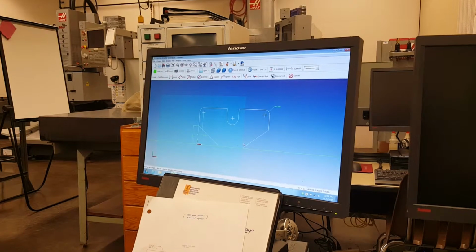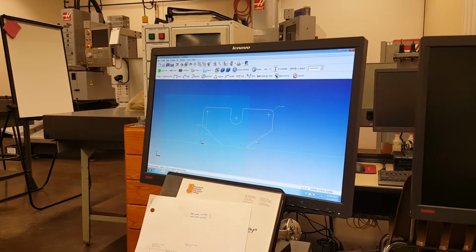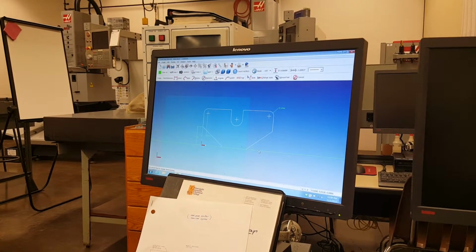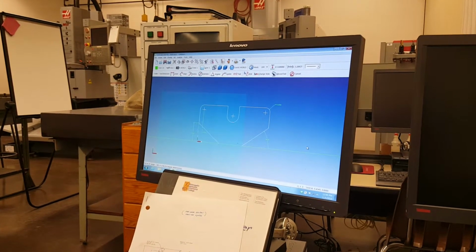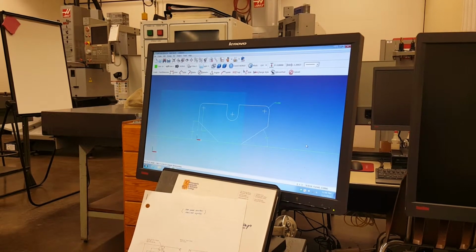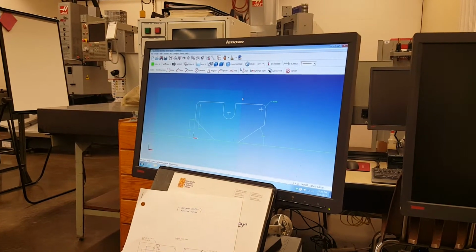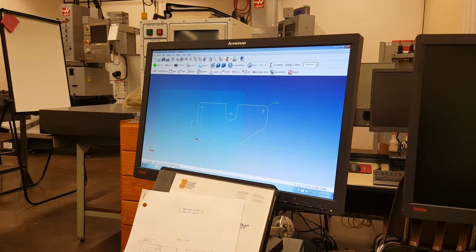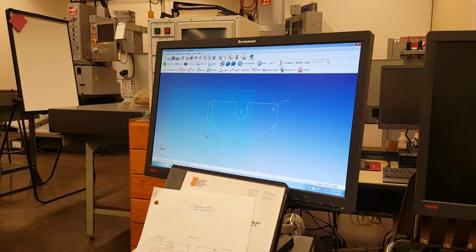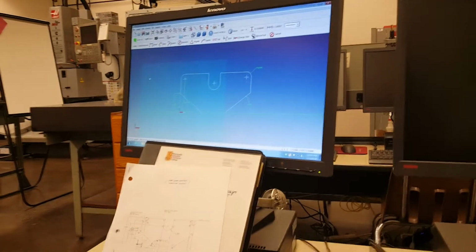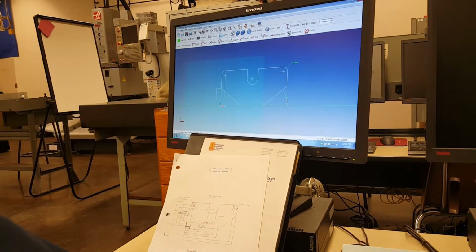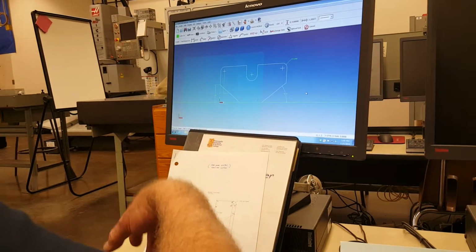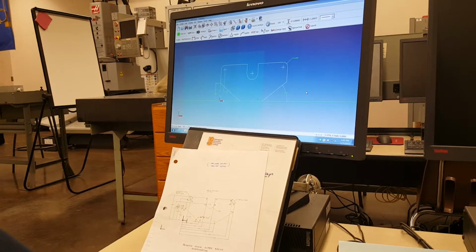What angle? Pick a line for angular. This one and this one. And it'll actually tell you the angle you've got there, if you needed to know that. What is that angle? It's 36 degrees, 52 minutes, 11.6 seconds. On the screen here it says 36.87 degrees. So it converts angles into decimals of a degree.